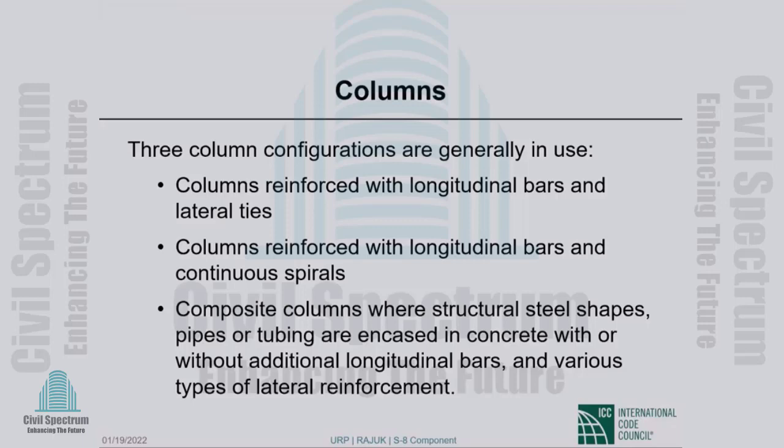When the column is circular and the beam is rectangular, the detailing of that joint becomes very complicated indeed. So that may be the reason, I do not know, but circular columns in buildings, other than parking structures, I should say, are relatively uncommon. And if the columns are not circular, the use of spirals is rather uncommon.